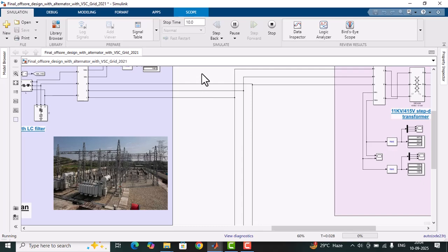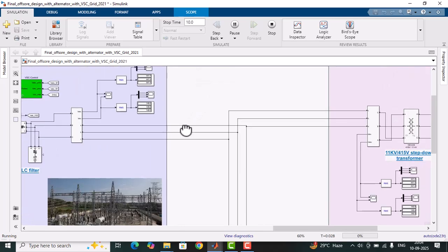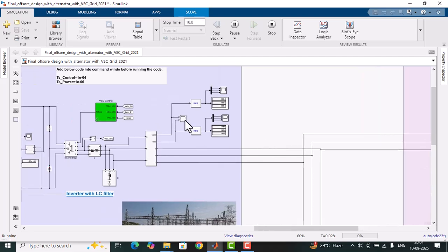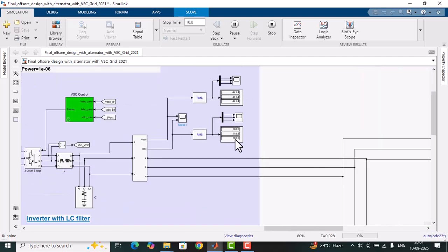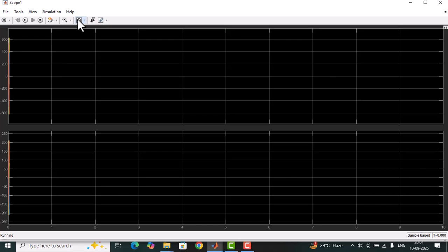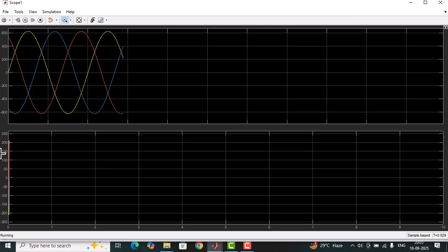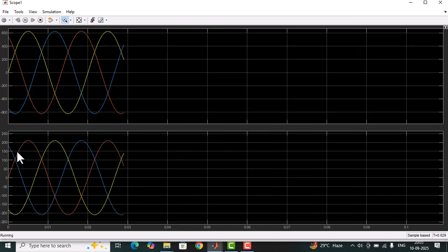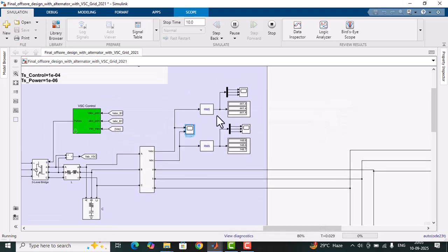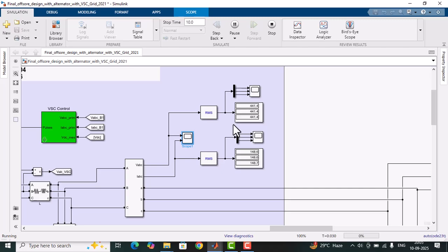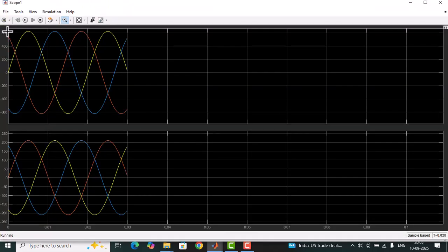Okay, and if you want to check the output of the inverter, you can check voltage and current. There is slightly higher ampere because of the circulating current flowing between the grid and the system, because we are trying to synchronize the grid and the inverter. So that's why we are getting slightly higher ampere. And here you can see the higher voltage, 600 volts, but it is the instant value. If you want the exact RMS value, the value that we get through our MFM meter, multifunction meter, it is this one, and this is the instant value. That's why it is slightly higher.